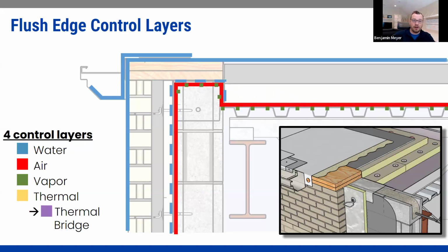Should it be an air and water barrier vapor retarder, where you have the vapor retarder here on the outside, all in one, or should we do it on the inside here? And I think one of the things we'll talk about is really the risk of the moisture inside this space making its way all the way back through here. So you essentially would always have damp CMU. And is that really a strategy you want? Or are you going to lose bond to this material over time? So we'll dig into that a little bit later.